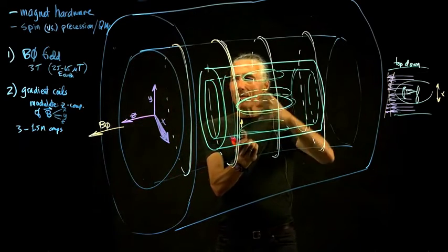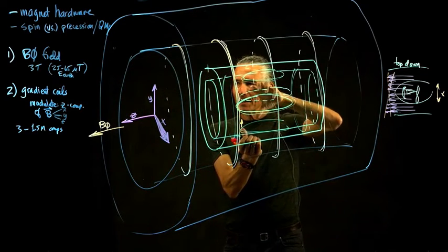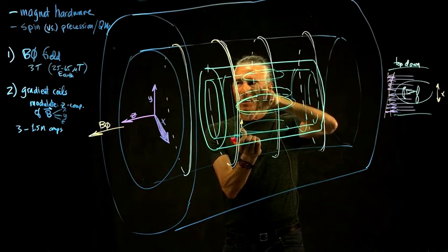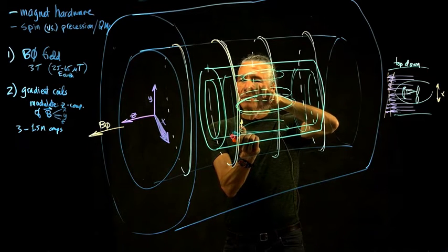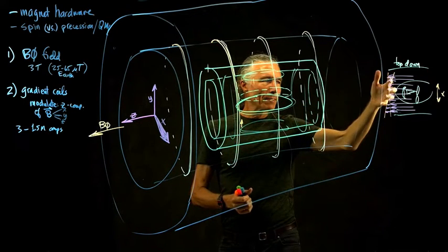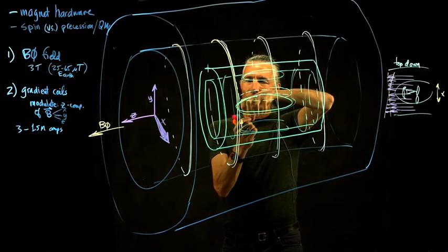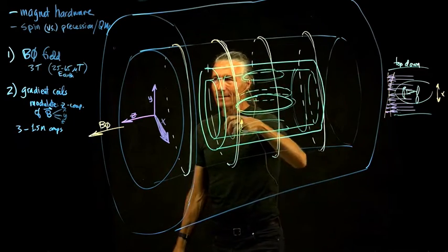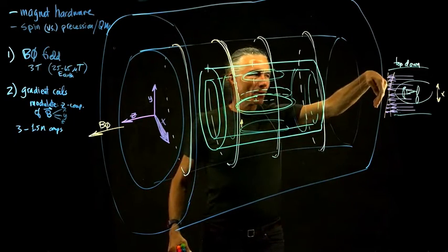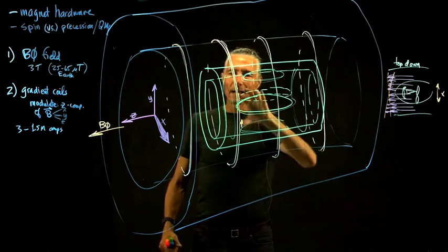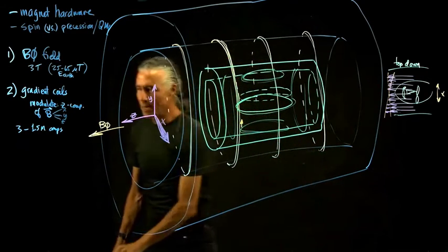Now, when you power them up, they generate a magnetic field, and that causes some pushing of the coil. And then if you rapidly flip the gradient to the opposite direction, the coil will try to move back and forth a little bit. And so that sound you get is just rapidly going back and forth like that and vibrating the coil. So that's what actually makes the noise.